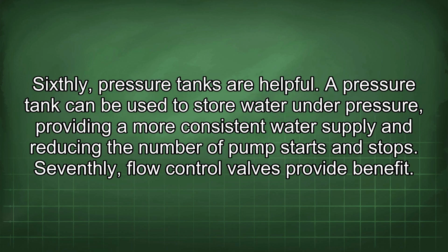Sixthly, pressure tanks are helpful. A pressure tank can be used to store water under pressure, providing a more consistent water supply and reducing the number of pump starts and stops.